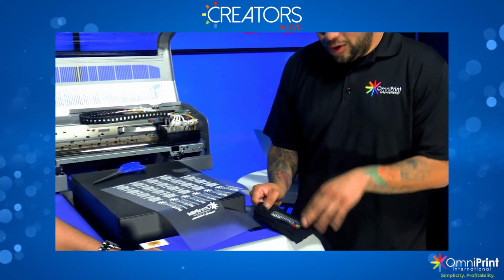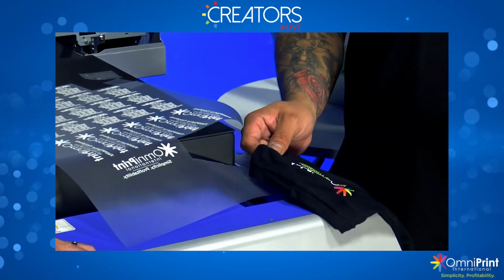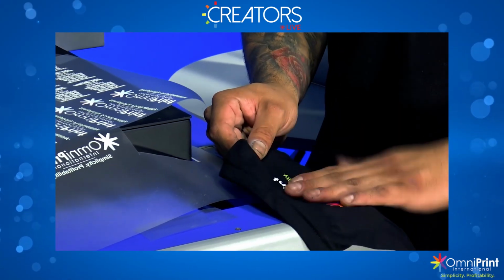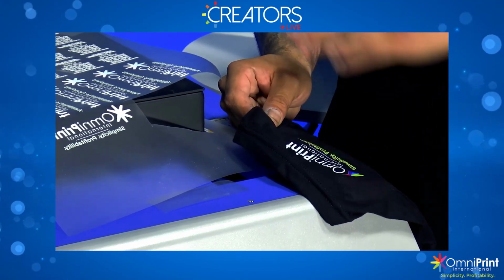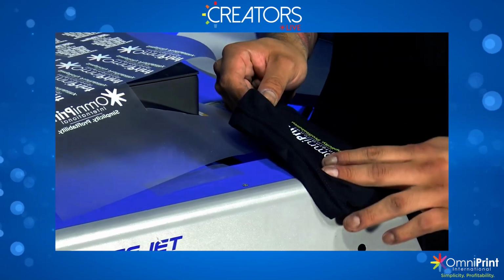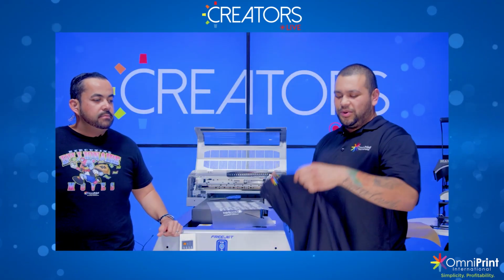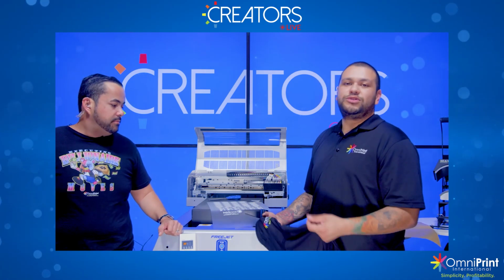If this was cold peel, I would have had to have let this sit here for 30 seconds, a minute, in order for it to fully cool down. And you want it cool to the touch. So once you're holding it down, if you still feel it's warm and you're using the cold peel, you don't want to rip that guy off while it's still hot or warm, or it'll rip the print right off as well. So that's one thing. The hot peel, we're able to get this and rip it off immediately. You don't have to sit there and waste a whole bunch of time waiting for it to cool down.